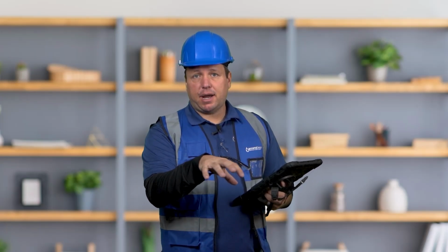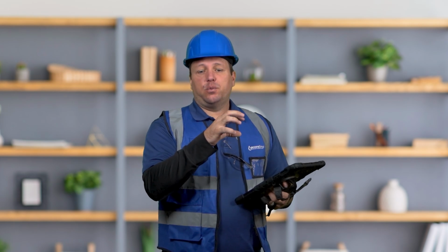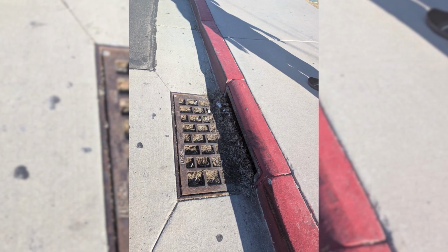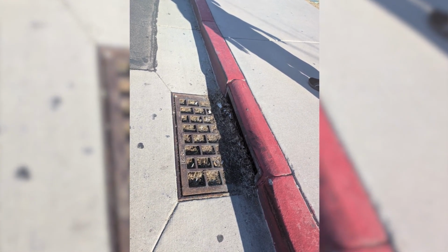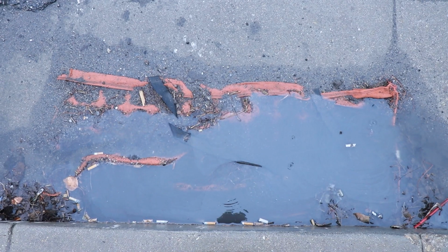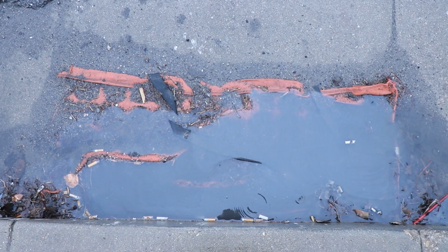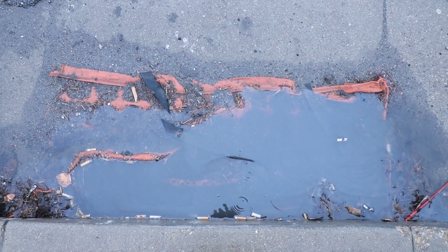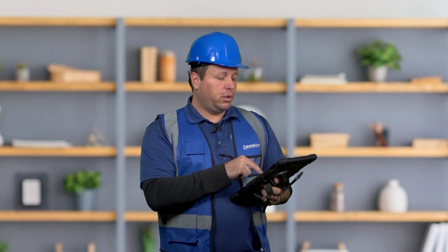So as you're looking at the inlets, both within the site boundary and the first inlet outside of the site boundary that the site will discharge to, those inlets also need to be protected. And when that protection reaches, again, if it's an inlet insert, if it's at 75% capacity, it needs to be maintained. It needs to be cleaned out. If there are inlet covers and there's a significant amount of dirt or debris on there that is going to inhibit stormwater from flowing through the inlet protection and getting into the inlet, then that would need to be cleaned off as well. This is where you would put those.